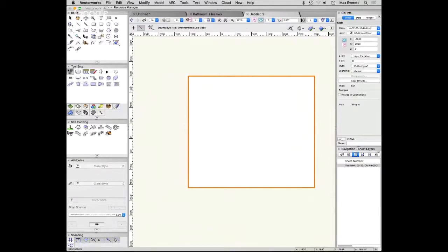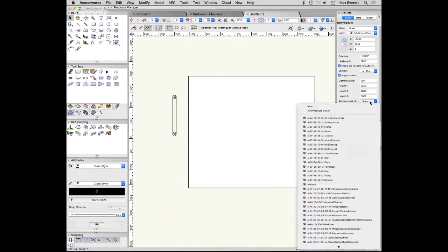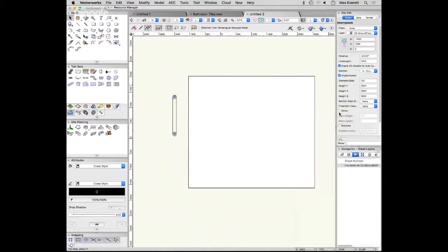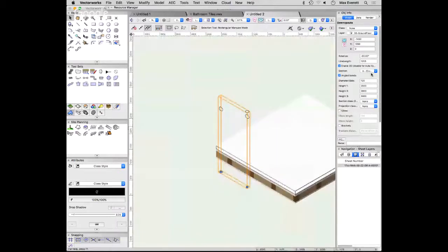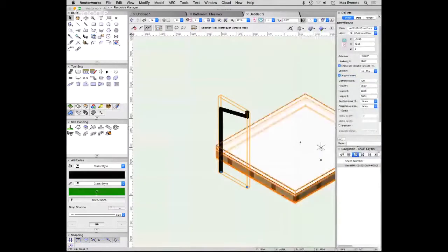So you can select rainwater pipe and drop in your rainwater pipe. You've got quite a lot of control over the first height, the second height, the diameter, and the class of the first cut and the second cut. You can have rounded elbows. I'll put that on a solid thing for now. Here we go. You can change the height to say 3 meters, for example.